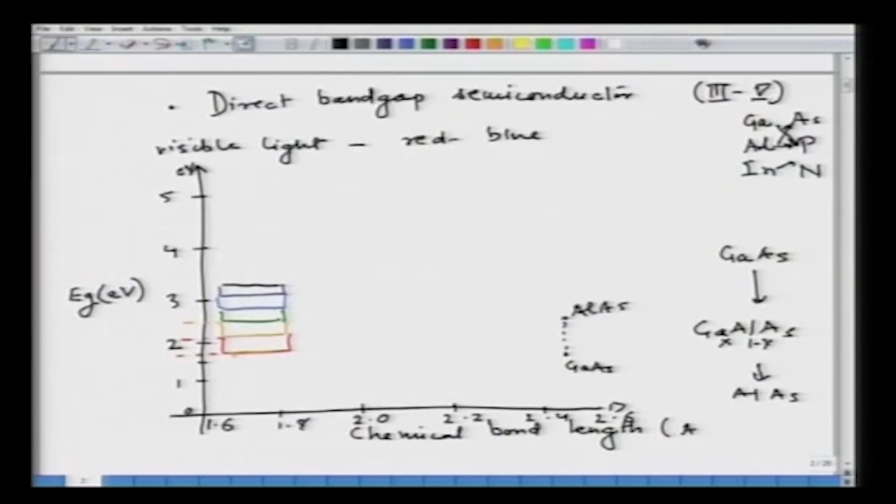So, it is a wonderful material for that, and for lattice matching it has a very good lattice matching. As we will see later, the lattice matching is going to be important for the material. It can change the band gap of the material if the material is not lattice matched. Let us look at the phosphide systems.